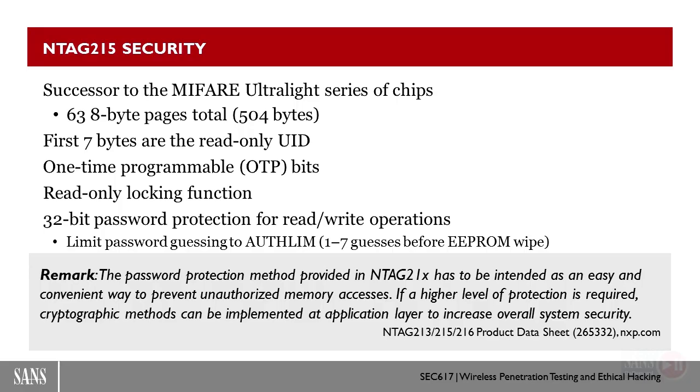The one thing that they did with these chips is for our authentication to be able to read, kind of like our MIFARE Classic 1K, you want to read a sector, well, you need to authenticate with a set of keys. In these cases, with the NTAG 215 chips, you have to authenticate and read with a set of keys, and if you don't have the right keys, it fails. And if you fail 7 times, it wipes the device. Huh. So this is like full disk encryption when you guess the password too many times wrong and it wipes the machine. Yeah, so you spend $15 on this figurine, and then you try to read it 8 times with the wrong key, and now it's just a useless hunk of plastic.